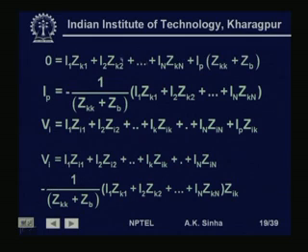And from that expression we can find out the value of Ip by dividing by Zkk plus Zb, which we have taken on this side, that is dividing this whole expression by Zkk plus Zb. So, we will get Ip is equal to minus 1 by Zkk plus Zb into I1 Zk1 plus I2 Zk2 plus In Zkn. So, this is the value of Ip that we get.